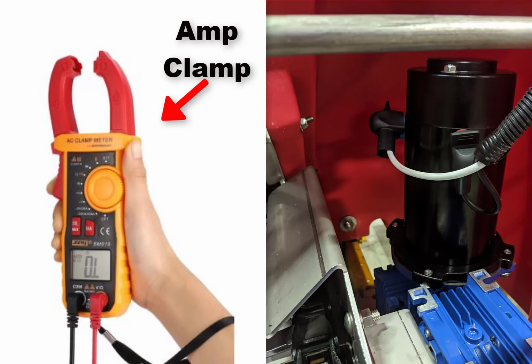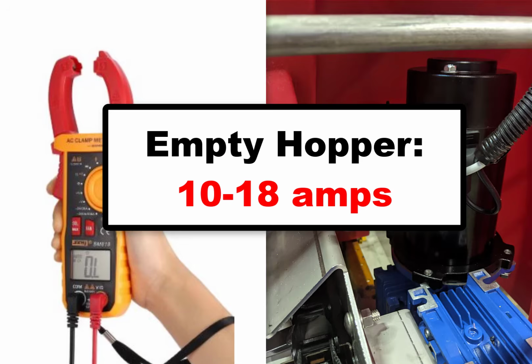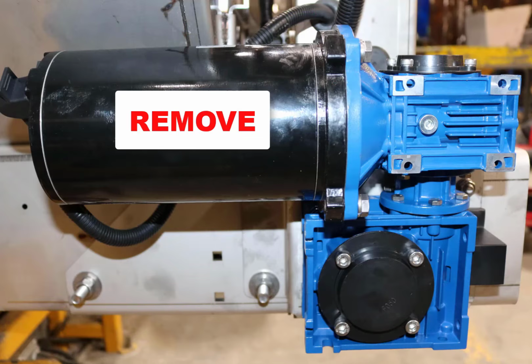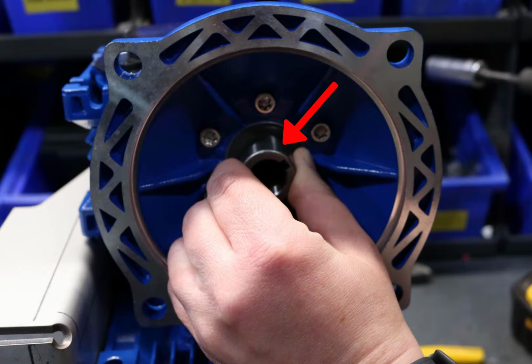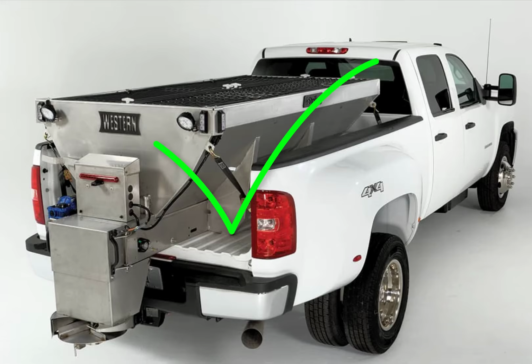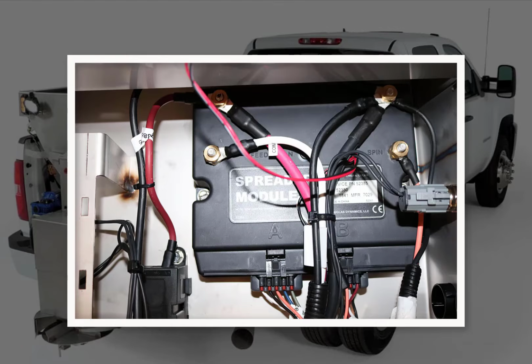Using an amp clamp, check the amp draw on the conveyor motor power wire. With the conveyor empty, the motor should draw between 10 to 18 amps. With the hopper loaded with sand, the motor should draw between 30 to 45 amps. Remove the motor and try turning the input shaft on the gearbox to check for any internal damages in the gearbox. With the conveyor motor disconnected, jump power and ground to the motor to see if you may have a defective conveyor motor. If everything tests good, try replacing either the spreader module or cab control.